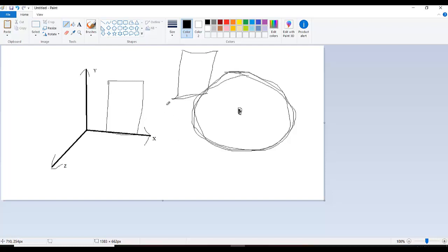Like you see a pulley, so you just draw a sketch of the pulley like that. If anybody has seen a pulley, he can understand that you can sketch a half. And if you are going to use a revolve command, basically you just draw a half sketch and then revolve it. You don't need to draw the full sketch.